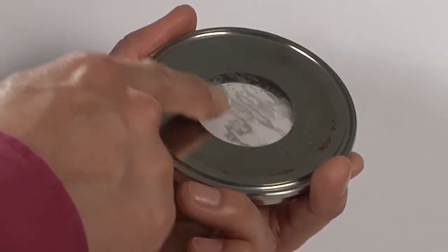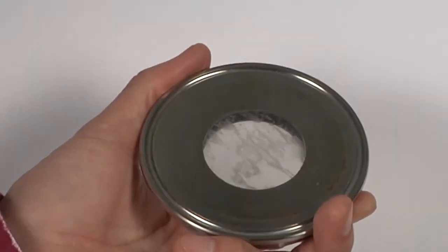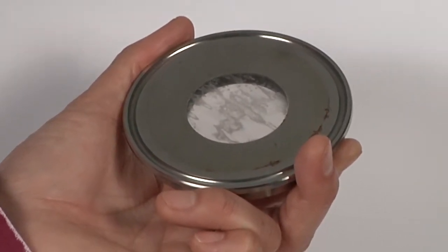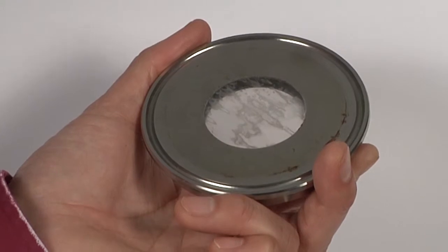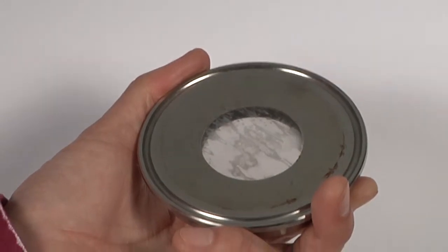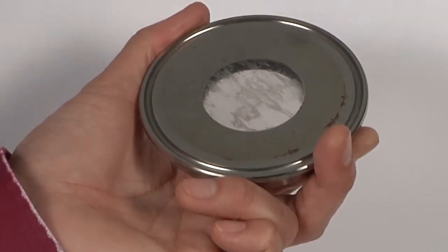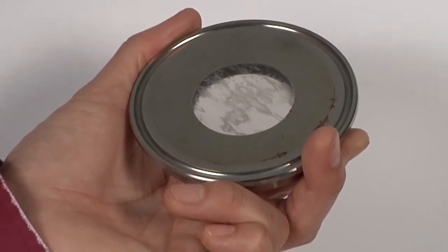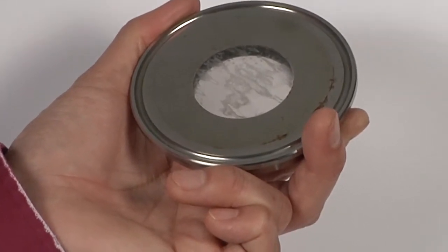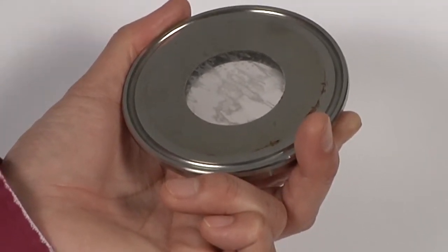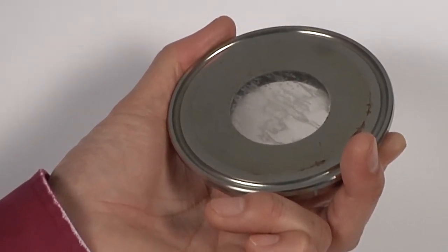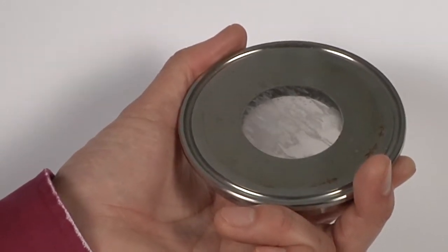And you can tell that the surface of this glass has already been starting to corrode away. But when a part of the glass in this kind of a structure is weakened, the pre-imposed stresses will cause some glass to shear and chip away. And you will see that right along the glass metal boundary when it actually happens. Okay? But when the glass chips away, that exposes fresh glass to more corrosion, and that goes on and on. So altogether, this type of side glass will lose much more material in a chemical corrosion scenario more quickly than the cheap annealed kind, because the chemical weakening of the glass will lead to chipping and physical separation of glass.